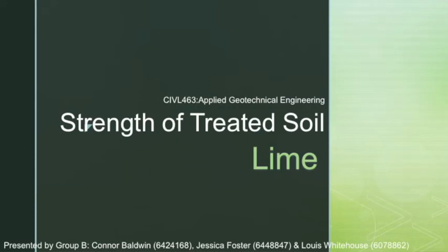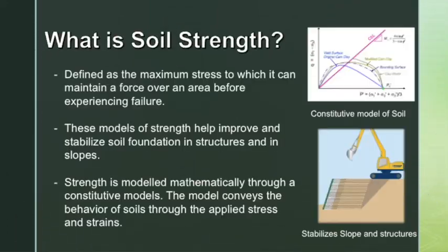Soil strength is one of the most important properties within geotechnical engineering, as the strength of a soil is the maximum stress under which it can maintain before experiencing failure, which determines its ability to support structures and slopes. Constitutive models of soil are used to determine soil strength by mathematically modeling soil behavior under load, by relating the applied stresses and strains experienced within the soil.